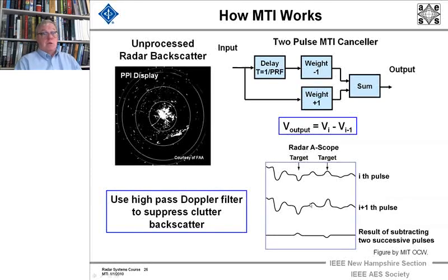Real targets are there, but here and here, they're like that fictitious ball bearing: ground, the Trump Center, the buildings along Atlantic City, the high-tension towers that carry electricity into this area, the ground that the lower lobes of the antenna and the side lobes see, and tall buildings, chimneys from power plants, which are in this area. Tens of miles across, they won't move. But an airplane will, and will give you a return.